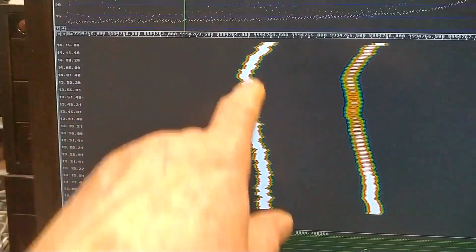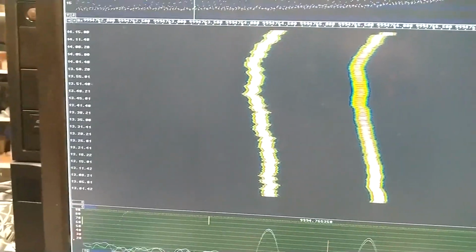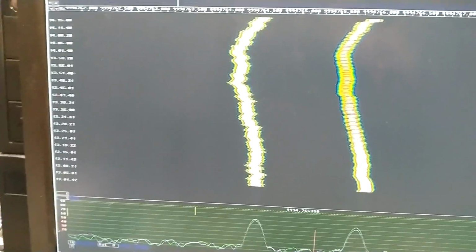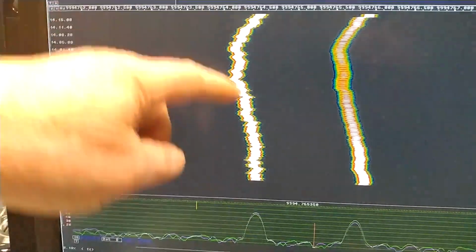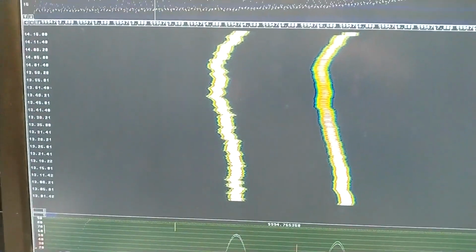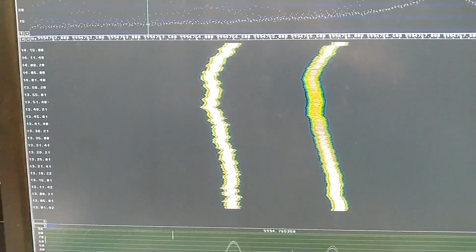This one is far more noisy, but in a very close separation to the carrier frequency. The slow movements belong to my 2 crystal oscillator. Could be temperature, could be power supply stability.